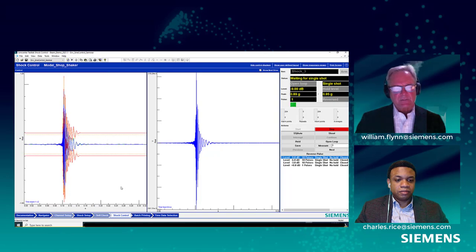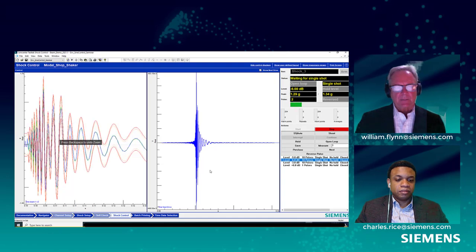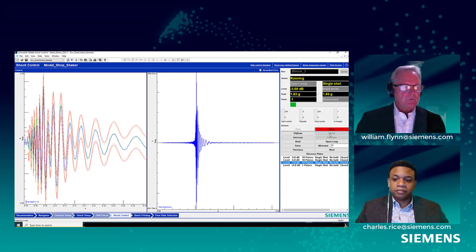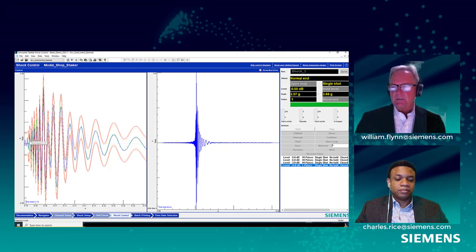Looks a lot like the measured pulse, but this is all based on an SRS. So maybe that measured pulse was from the SRS response. Can't remember for sure, but we'll go to the next level. We'll pulse it. Let's zoom in on this here so we can see the update. Go to next, shoot, shoot, shoot. You see a little bit of update. Go to next to full level. Got one pulse at full level, and there's our response. So everything's within limits. We had 0 aborts, 0 alarms, so everything's within our prescribed limits.